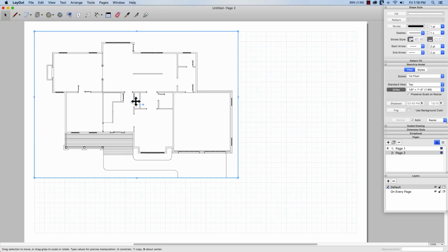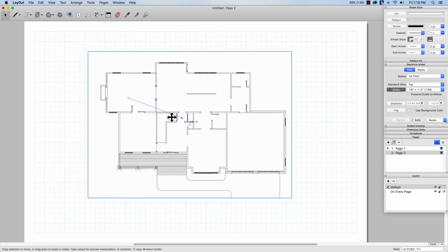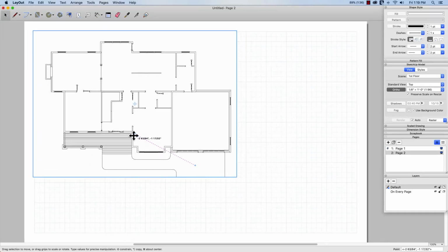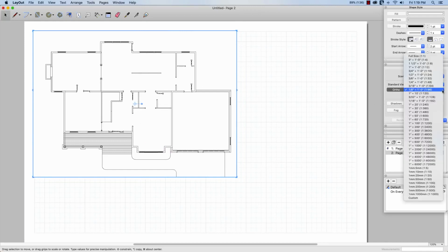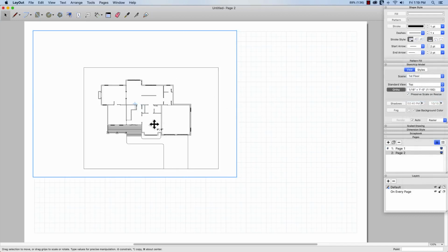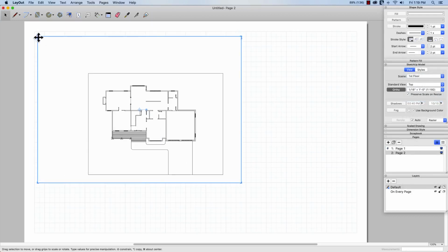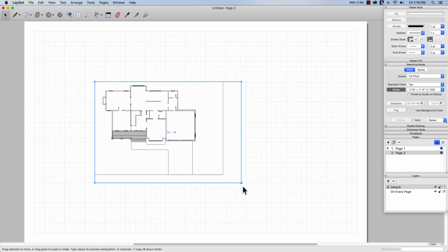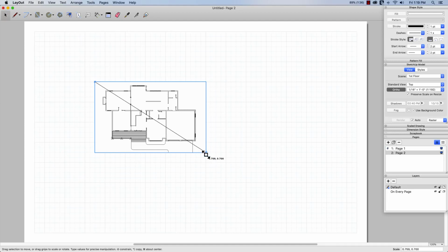While this is 1/8 inch, which is probably what I'd want to put out, if I was making a drawing of this, I'd put this in the middle, title bar over here. But for this example, I'm going to make it a little bit smaller so I can see my two floors side by side. So we'll drop down to a 1/16 inch equals a foot. And it'll give me a smaller, but still very usable size there. Okay, so I'm just going to crop that back down.